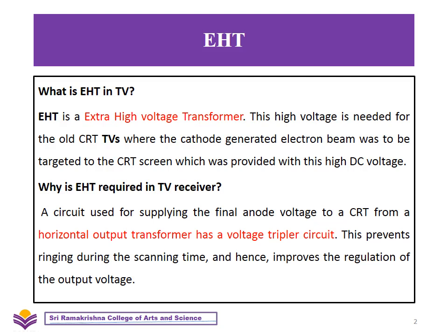The synchronizing pulse consists of the horizontal pulse, equalizing pulse, and vertical synchronizing pulse, which is given as an input to the high pass filter. The high pass filter will process the horizontal synchronizing pulse. The horizontal synchronizing pulse is nothing but a spike pulse, which is obtained as an output of the high pass filter circuit.